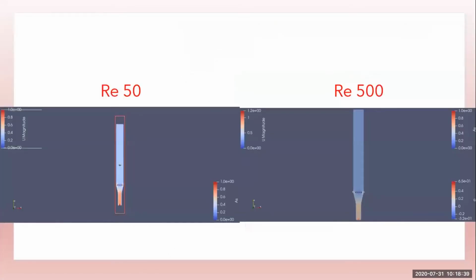So here's a visual representation of the simulations we ran. You can see the interaction between the fluid and the particles in the fluid. When the viscosity is high, that means the Reynolds number is low, so most particles are not able to move or translate as much. Hence you can see on the left screen, at Reynolds number 50, not that much current is forming.